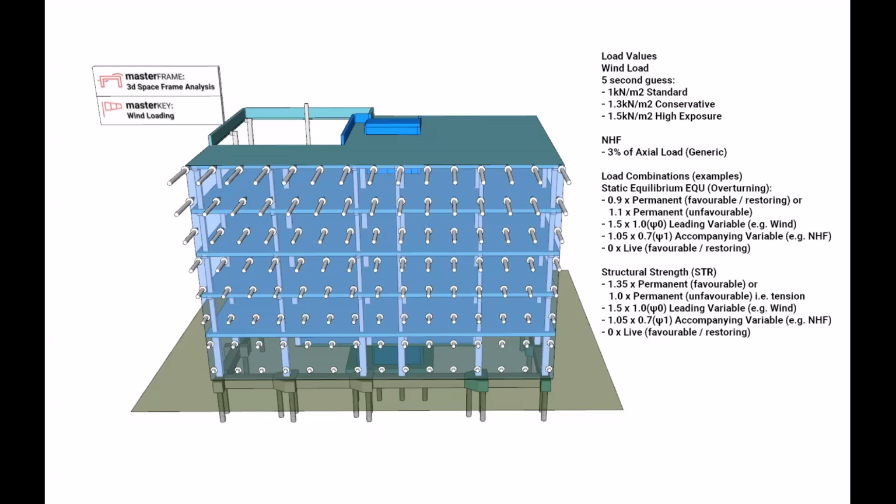For equivalent horizontal forces, aka notional loads, likewise, we can use some preliminary figures, and within Eurocode 1, we can take 3% of the worst case load combination for a given structure as a generic figure to be applied horizontally at each floor. But more in-depth calculations in the Eurocode get more specific about the application of loads on both steel and concrete frame buildings. So again, the iStruct has a good bite-sized technical note covering equivalent horizontal forces as well.